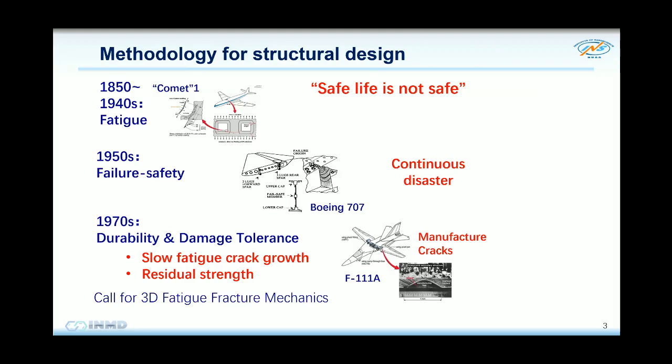From Wöhler's age to 1940, before the Second World War, a lot of airplane designs used the safe-life principle based on fatigue theory, but they found the safe life is not safe. So cracks and these kinds of things occur. Later, based on fracture mechanics theory, we developed the durability and damage tolerant design paradigm.